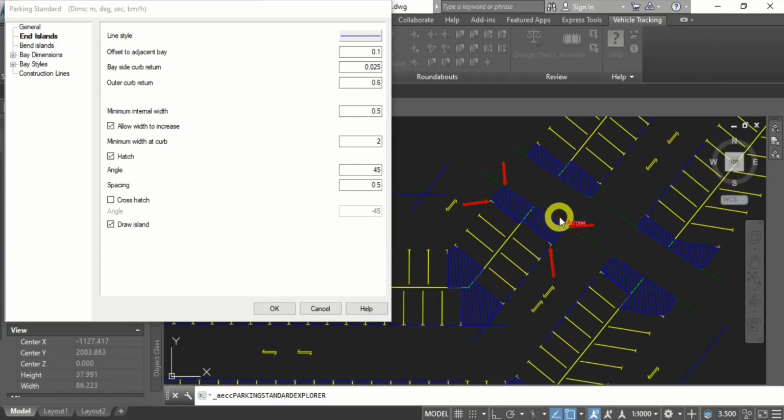So you need to look at that in your local standard, but normally for an access road with a minimum width of 6 meter and low frequency of movements, or for an access road with a minimum width of 10.5 meter with high frequency of movements, a minimum radius of 0.5 meter will be appropriate.